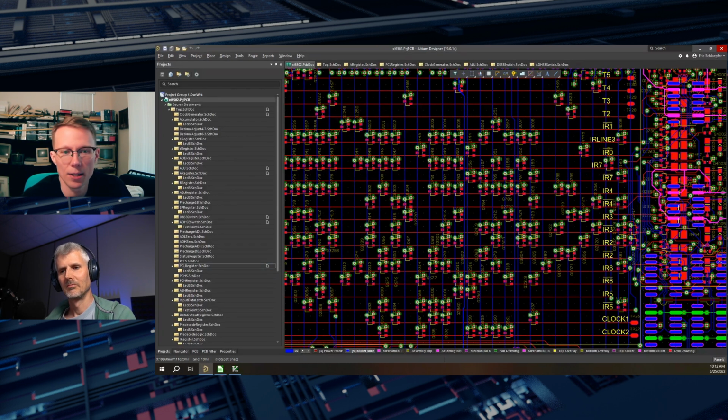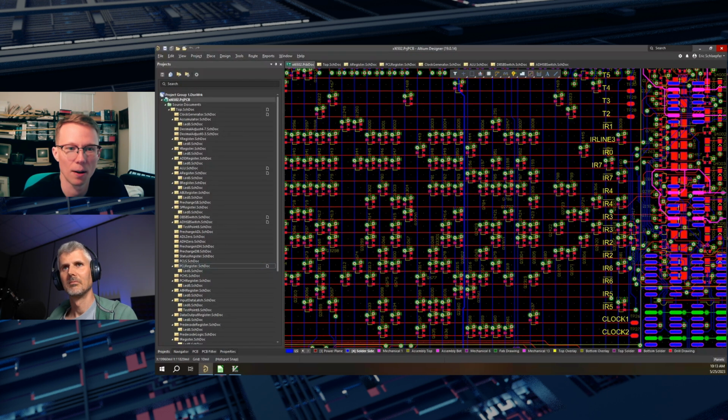Stage two is a more complicated set of test vectors. Again, it's 6502 instructions, but the idea is to exercise all possible instructions with all possible memory addressing modes and carry bits and all those types of things. The challenge was, I actually started with somebody else's open source 6502 verification, and it was designed for someone's 6502 FPGA project.